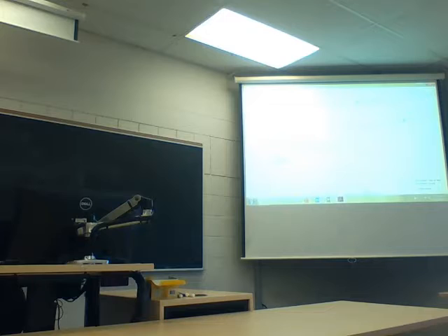Here's a two-stage centrifugal compressor. Same concept as any other compressor. Two stages means we compress it twice. We take it from one impeller and drive it into the next impeller and compress it some more. That's basically all a two-stage is: we're taking two steps to the final compression. All right. So a multi-stage one will be more than two.